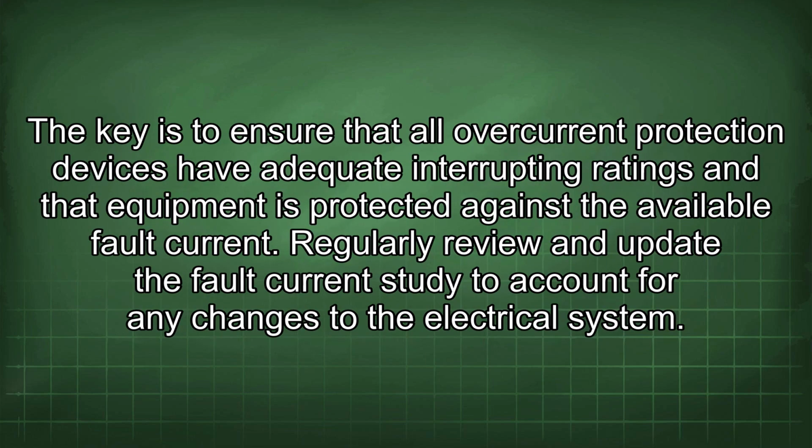The key is to ensure that all overcurrent protection devices have adequate interrupting ratings and that equipment is protected against the available fault current. Regularly review and update the fault current study to account for any changes to the electrical system.